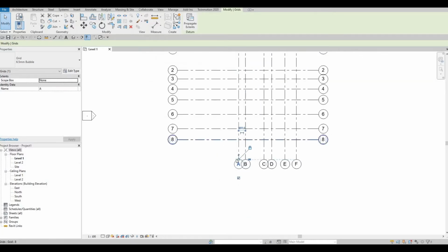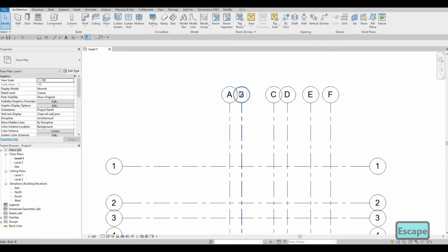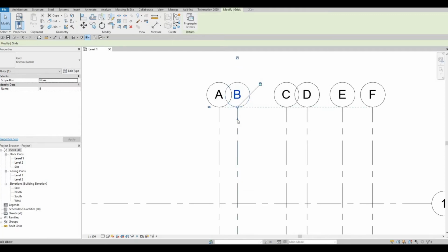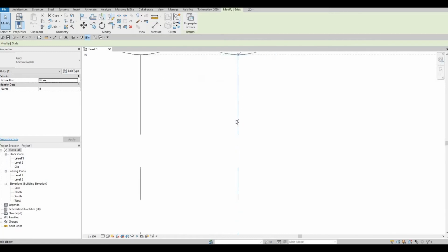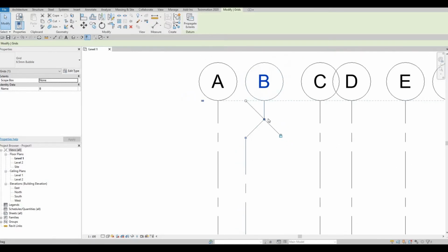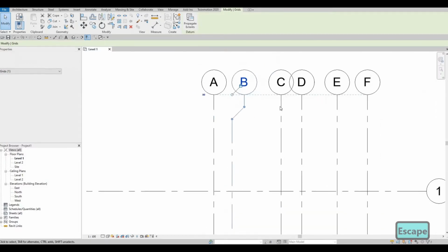And there you go. For some reason, if you don't want it to be overlapping, click on the grid bubble, and you can see here, add an elbow. It's a small zigzag on the line, and once you click that, it will create this zigzag effect, or an elbow, we call it.